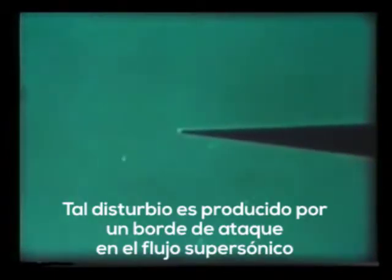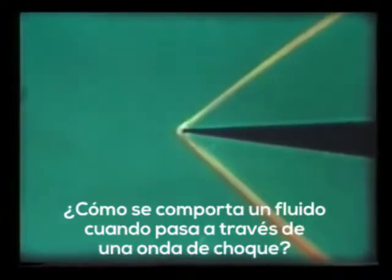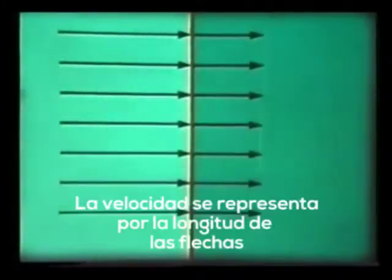Such a disturbance is produced by a leading edge in supersonic flow. An oblique shock, the bow wave, is formed. How does the flow behave as it passes through such a shock wave? Consider first a diagram of a normal shock wave. This, at right angles to the flow, always slows it down from supersonic to subsonic. The speed is represented by the length of the arrow.